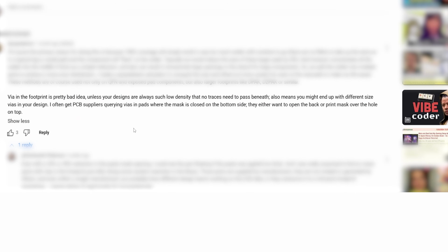This next question comes from the bottom terminated components video, and this question comes from superfan Super Jim. Super Jim writes, via in the footprint is a pretty bad idea unless your designs are always such low density that no traces need to pass beneath. Also means that you might end up with different size vias in your design. I often get PCB suppliers querying vias in pads where the mask is closed on the bottom side. They either want to open the back or print mask over the hole on top.